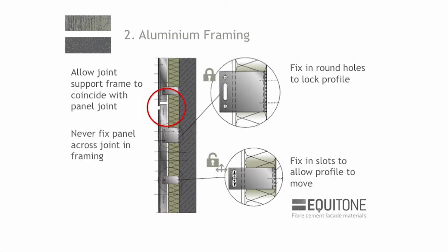So what is dramatically, and this is probably one of the most important slides for us and for you guys, is that wherever your rails are joining and meeting each other, it must have a relationship to the panel. And we would always ask for a 20 millimeter gap here. 10 would suffice. Okay? However, if you guys insist on doing 20, at least you're going to be guaranteed it'll end up 15. Alright? If you insist on it being 10, you'll be lucky if you get 8 or 9, 7, 6, you might even get down to 5, and then you're going to be in trouble.